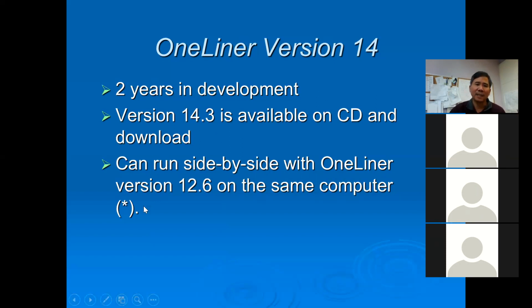With an asterisk here, be aware that if you save a file in version 14 and open it in version 12, something not right may happen. If you have new features that you enter into version 14, those features may be lost in version 12. So be aware of that. Otherwise, the fault simulation and most of the other commands should work the same.